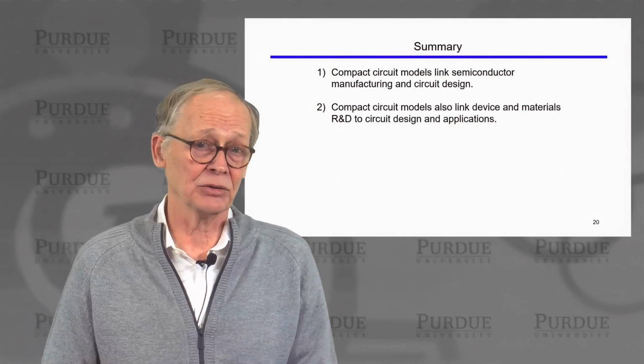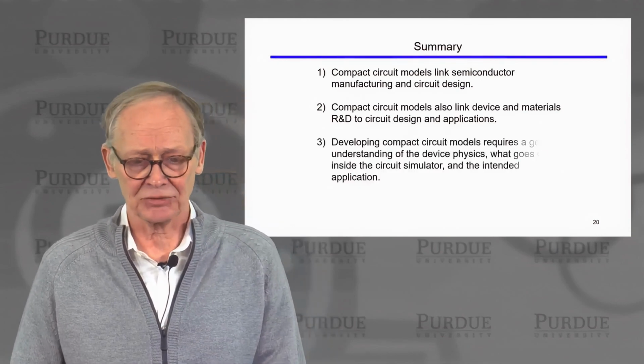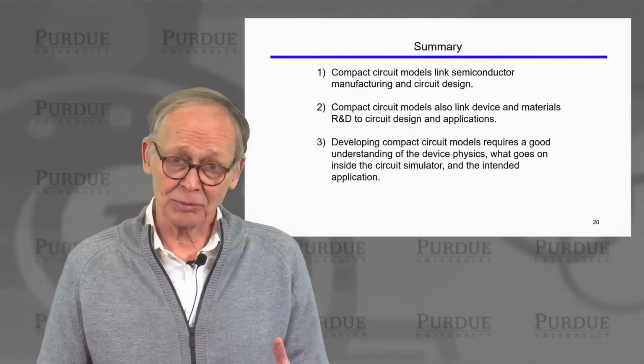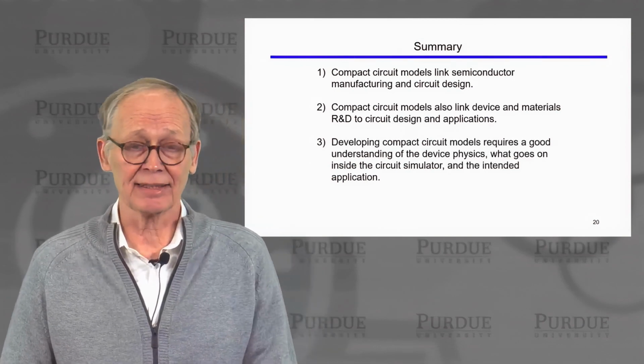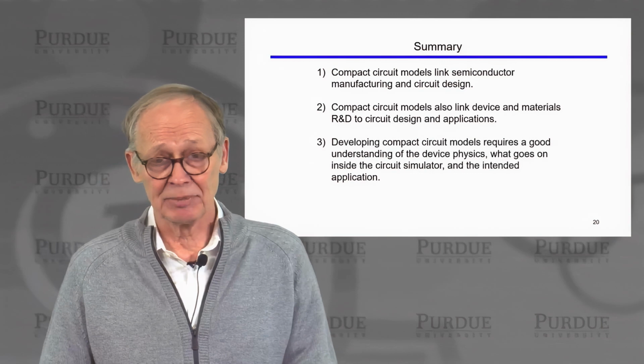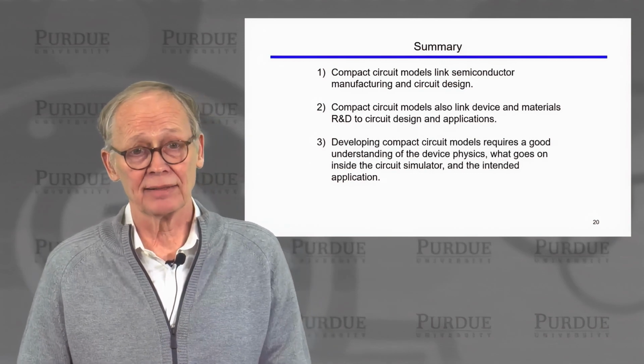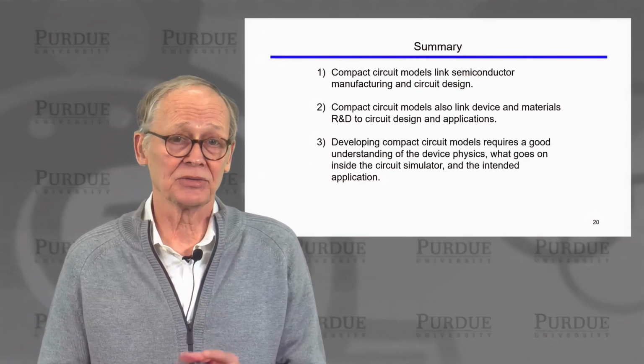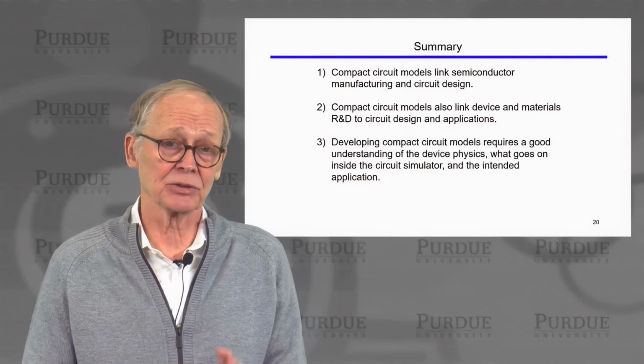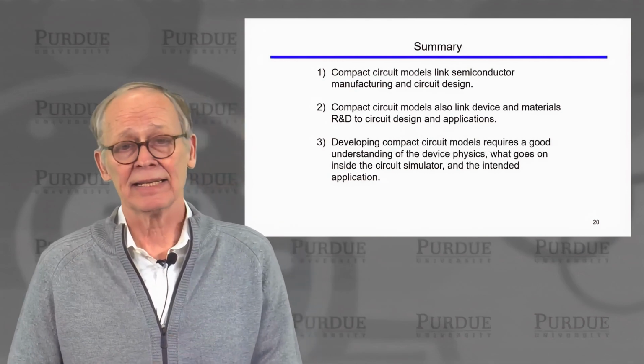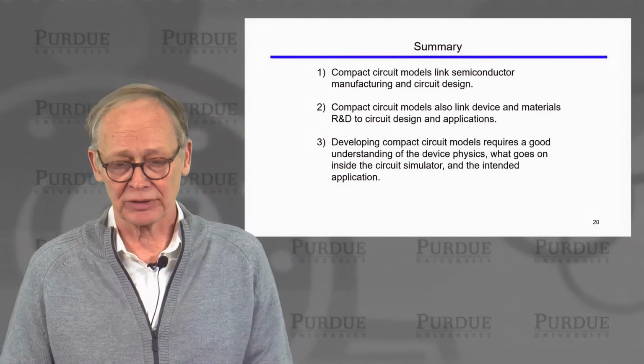And for that, you can make use of less sophisticated compact circuit models. Developing a new model requires a good understanding of the underlying physics, but it also requires an understanding of how the circuit simulator solves the circuit equations so that you can make sure that the model behaves well in the numerical solution of the circuit equation.